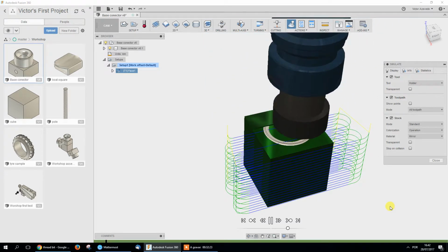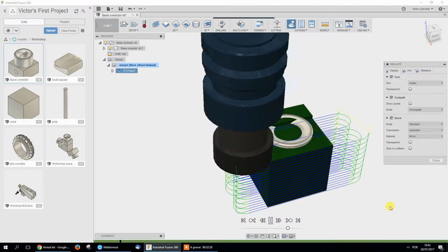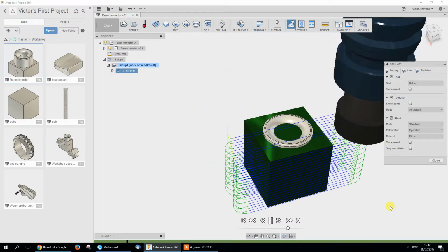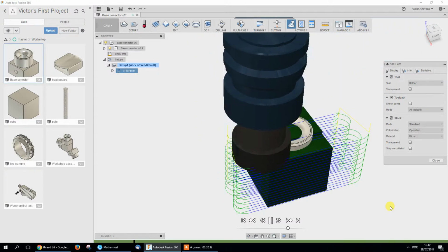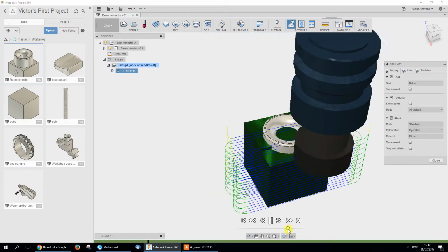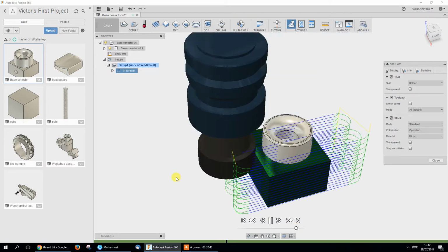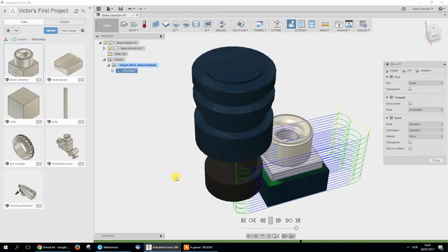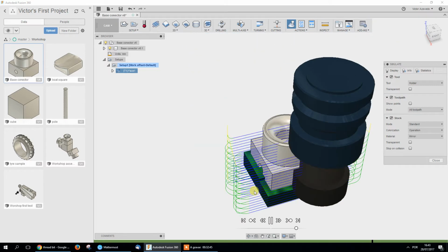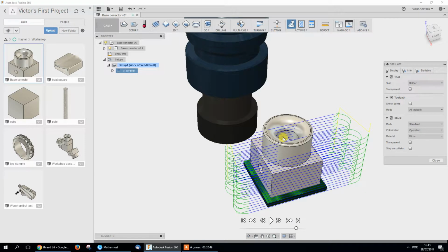The white area is your part, and it's going to be removed fully. And it's only removing 3 millimeters each passage. So if you define it as until the model bottom, you won't have anything. Okay? It will only leave the part where you grip the part.